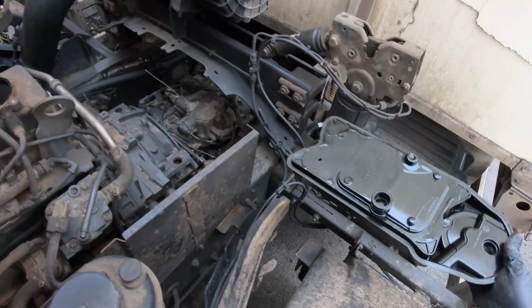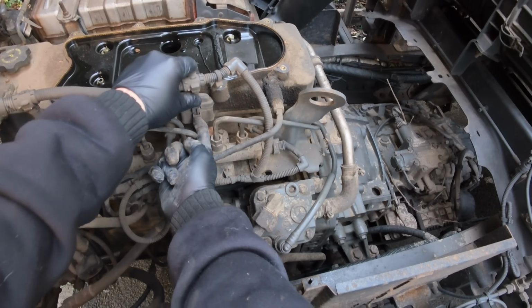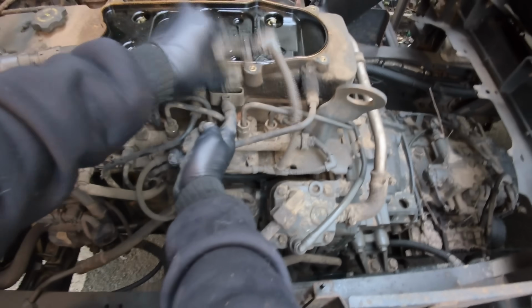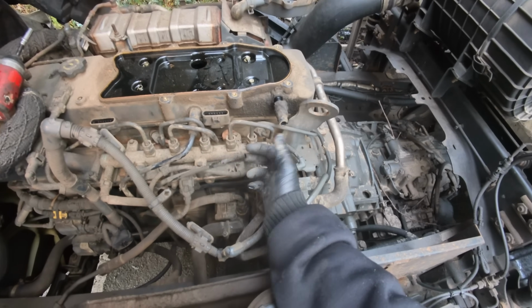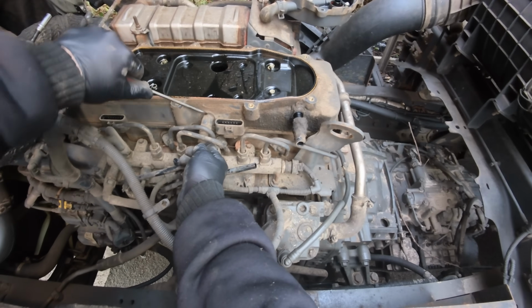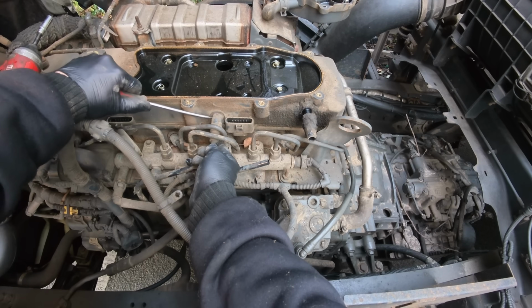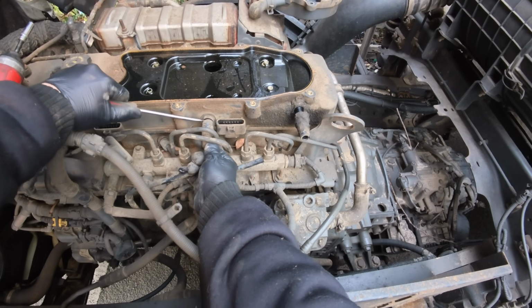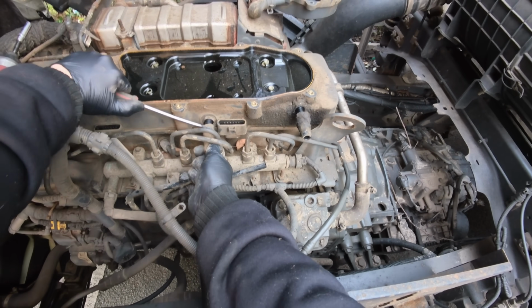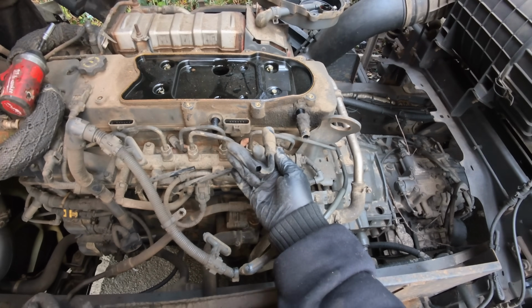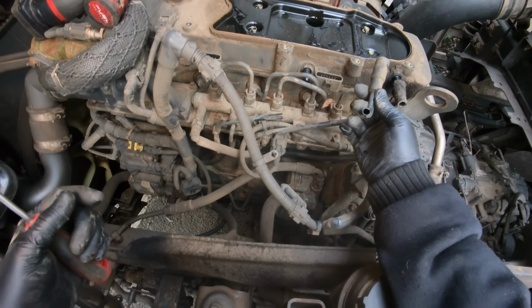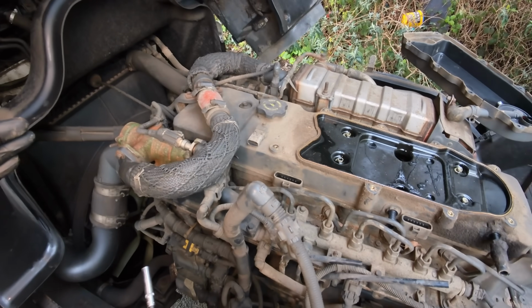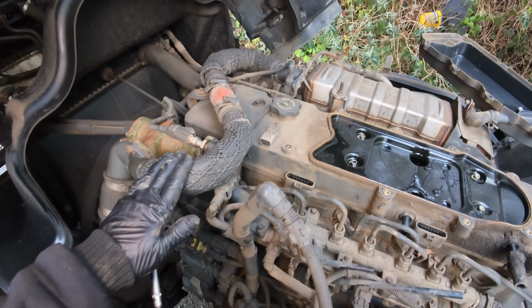So that's our crankcase filter. We'll have these electrical plugs off here. Just managed to snap this off. It's the most brittle plastic I've ever touched, so we'll be a bit more gingerly with this. See what I mean? That's unbelievable. So that's two pipes I've got to get now. Yay! So the only thing left we've got to take off now is this pipe here from the EGR cooler to the EGR valve.